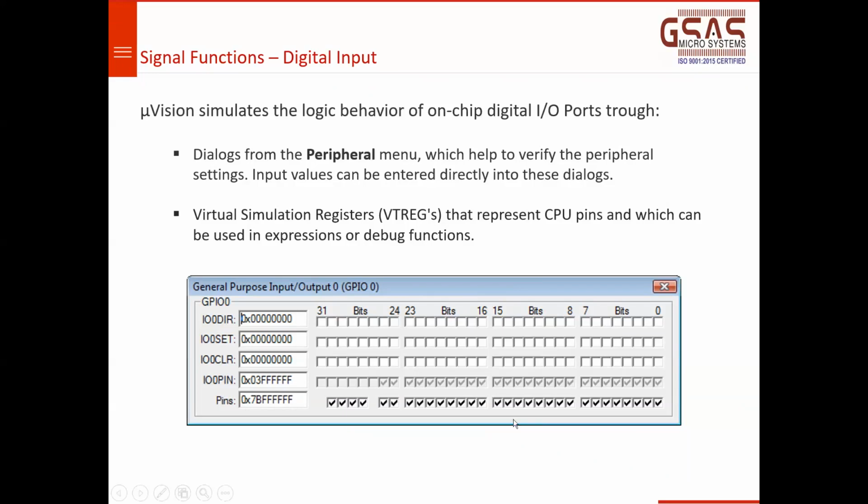I'll be demonstrating this. Suppose a particular port pin is also connected to the external interrupt, so I can simulate my interrupts here. How is an external interrupt generated? Usually when you press a switch or toggle something like a joystick. Because there is no hardware, I can still drive that pin. The embedded application keeps polling that particular interrupt pin.